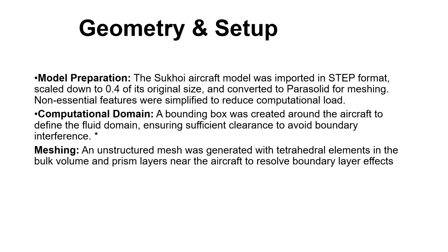The aircraft geometry was first prepared by importing it in STEP format. Since high fidelity models can be computationally expensive, I scaled the model down to 0.4 times the original size and simplified unnecessary features. The computational domain was created using a bounding box, ensuring sufficient clearance between the aircraft and the domain boundaries to avoid artificial interference.